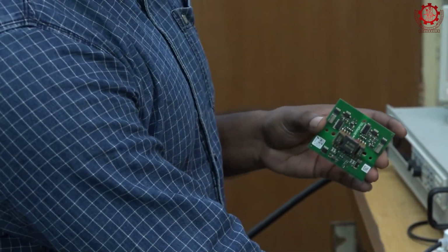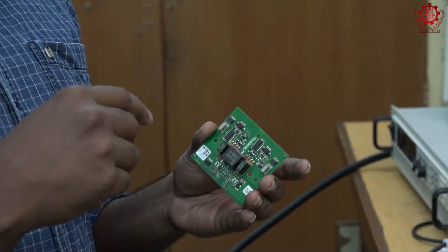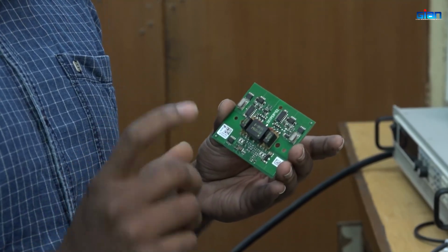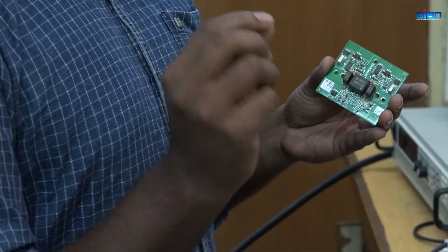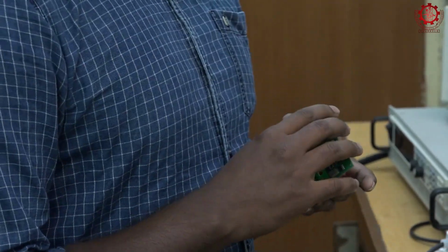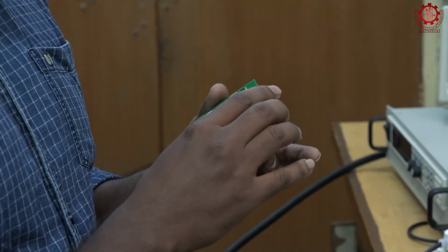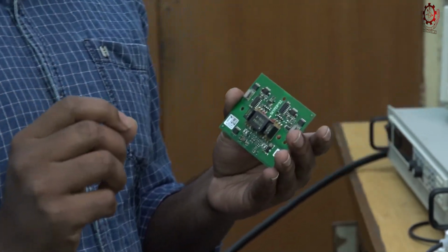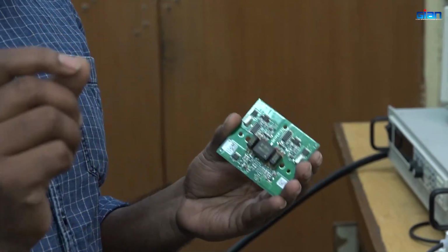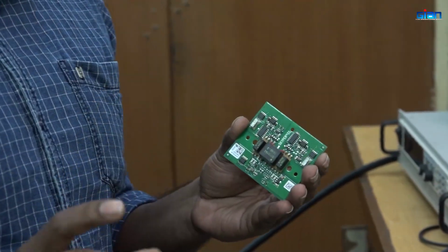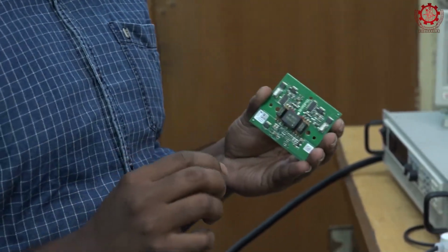If both switches were on at the same time there would be a short circuit, so it protects by providing a propagation delay between the two switching sequences. Also, it has short pulse detection, so if a pulse is shorter than 365 microseconds, it will not allow it.